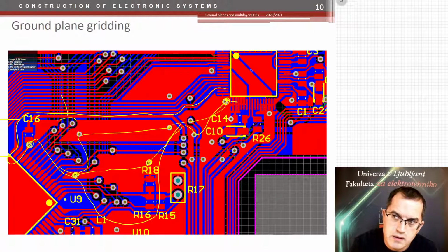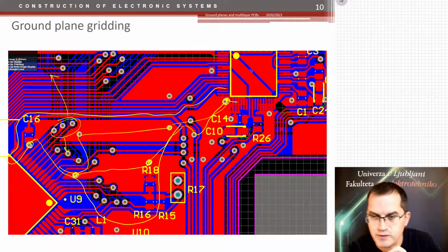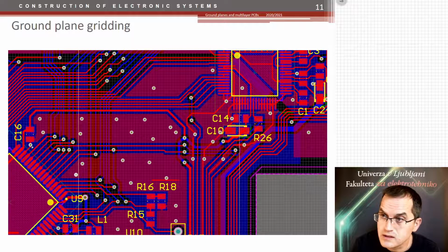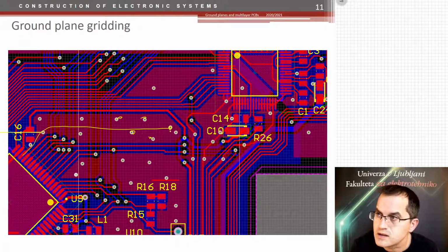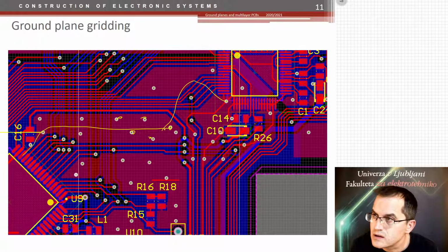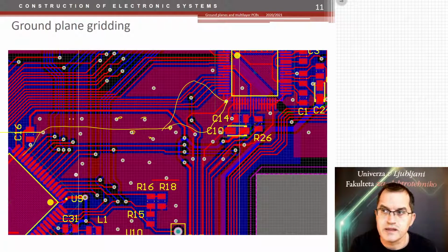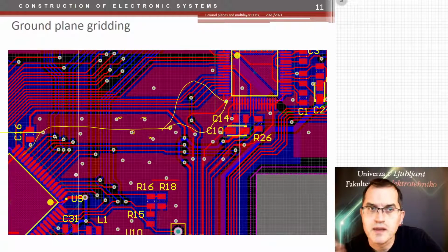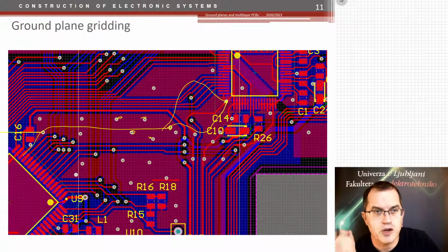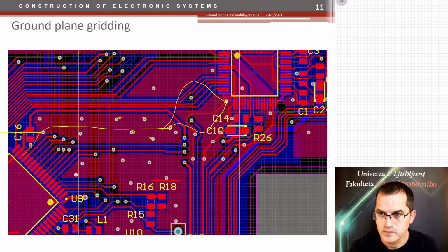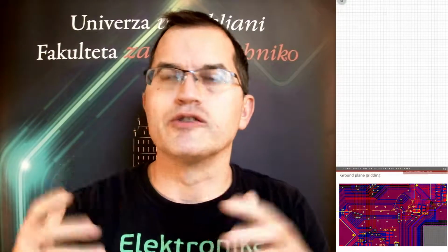I can move these lines up, move these wires down, and I can maybe make a space for that part. So that's the solution. As you see here now, the return current flows from here and goes directly there, changes layers at many wires, going down and returns back to here and here. So just by moving lines a little bit, I can provide more space for the ground plane. And the ground plane should be placed on top and bottom, and then it should be well connected together with many wires. And by that, I make a so-called ground plane grid.